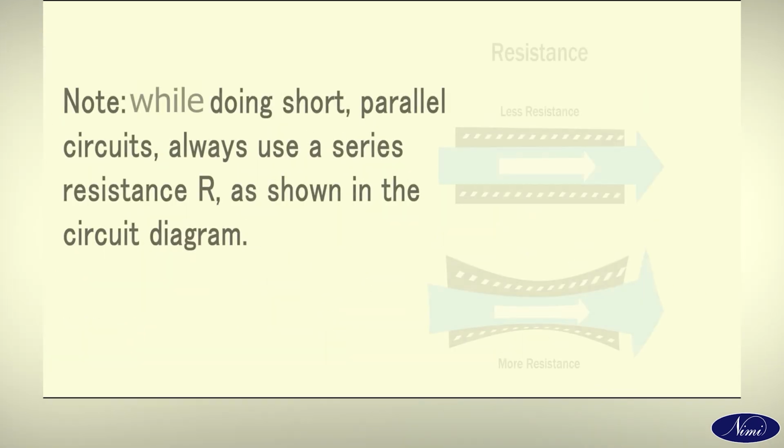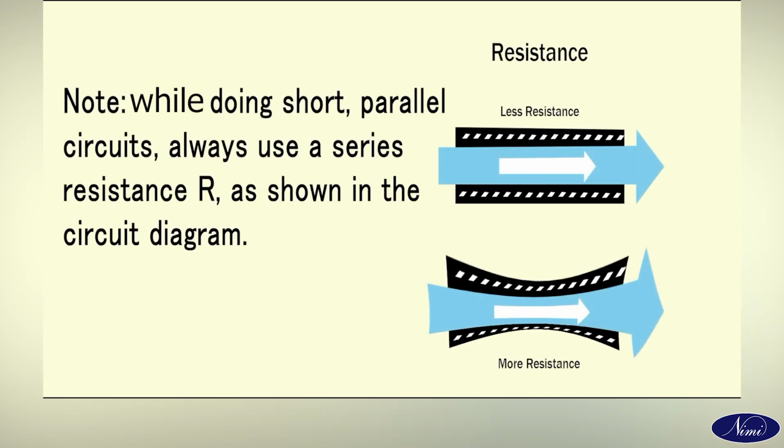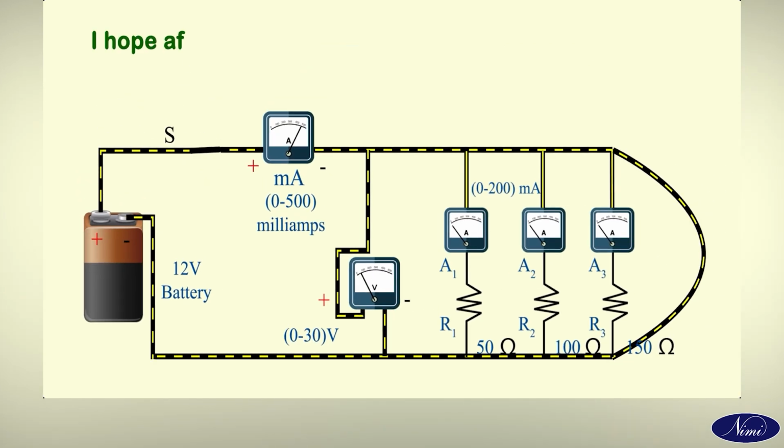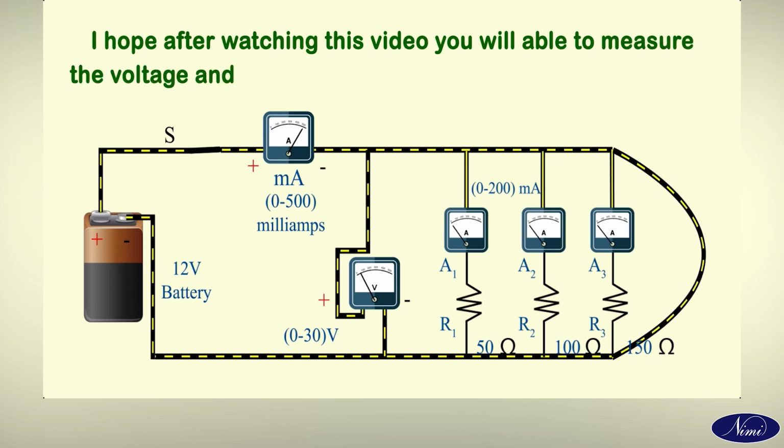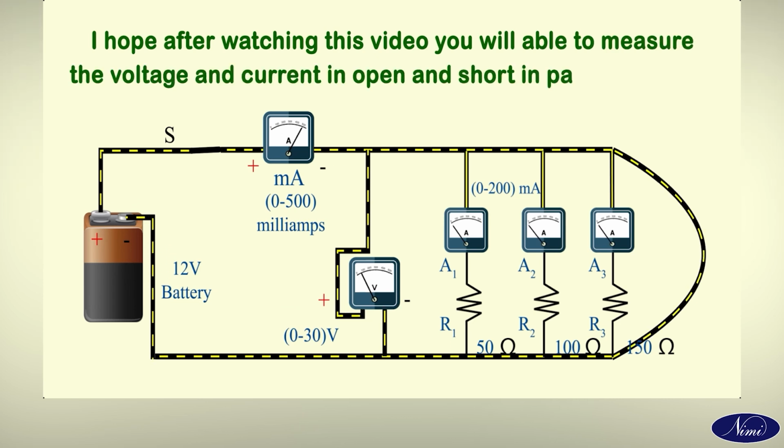Note, while making a short in parallel circuits, always use a series resistance R as shown in the circuit diagram. I hope after watching this video, you will be able to measure the voltage and current in open and short parallel circuits.